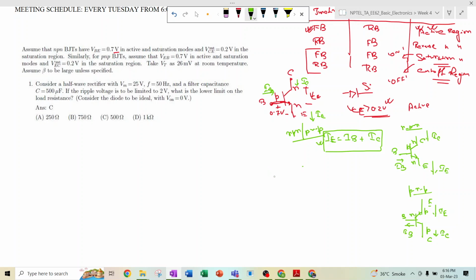Basically, what is the fundamental thing, that is how we can operate a transistor, that I am showing. This is some bias voltage VCC. Either we can take the VBB from here, then it is called a single voltage source. Using the single voltage source, we can apply the bias both to the collector terminal and the base terminal. Otherwise, if we want to make it a double source, then we apply two batteries, or two different potentials, in the collector and the base region.